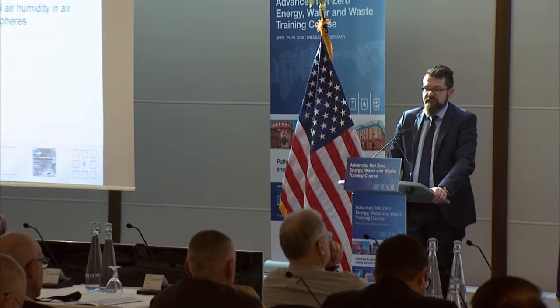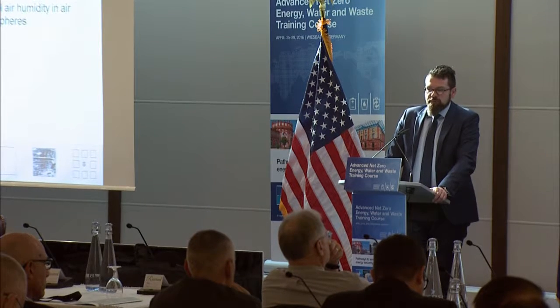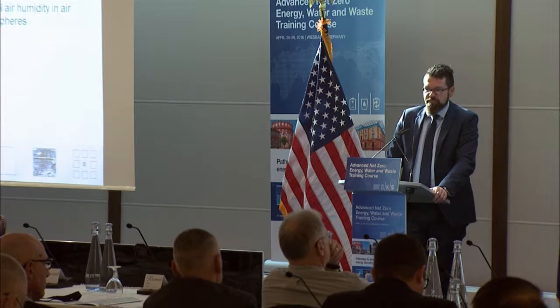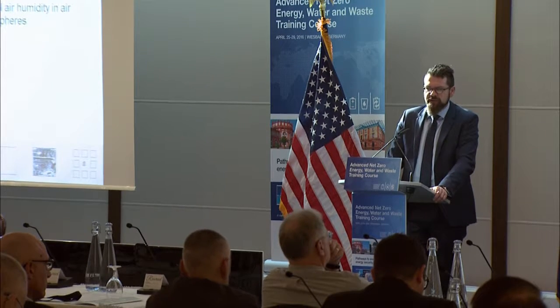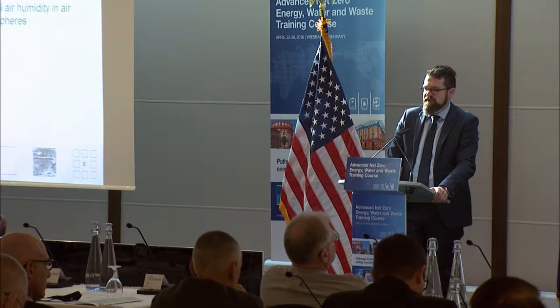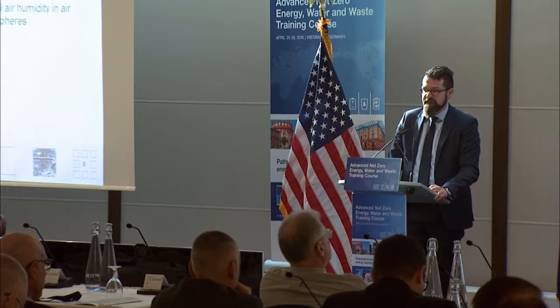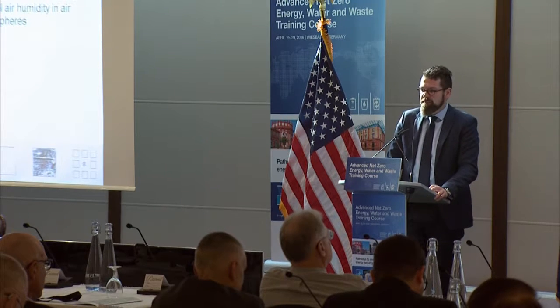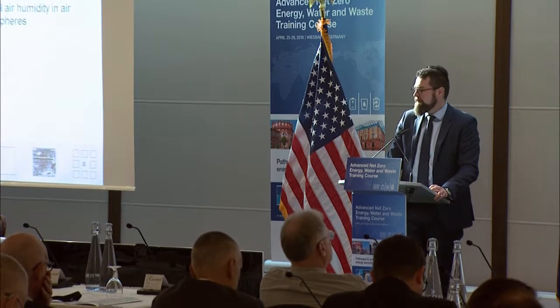And these different kinds of applications require different temperatures. So here's a mistake inside. The first application should be domestic hot water. We need temperatures higher than 60 centigrade to have Legionella prophylaxis. We have space heating. You need temperatures between 35 and 90 centigrade, depending on the heating system in the building and the size of the heating source inside the room.